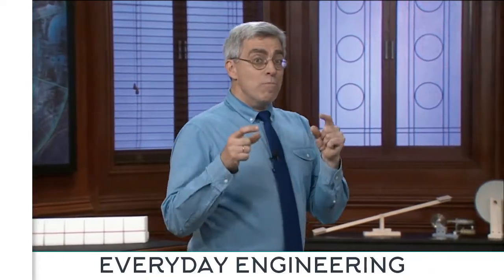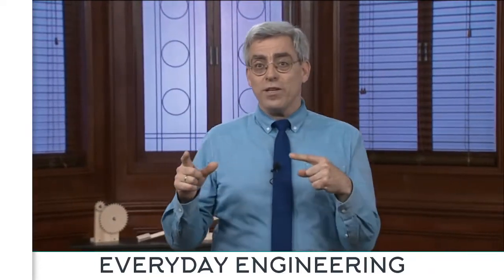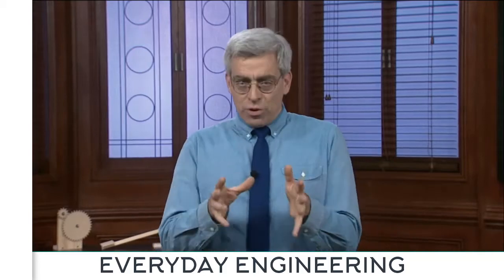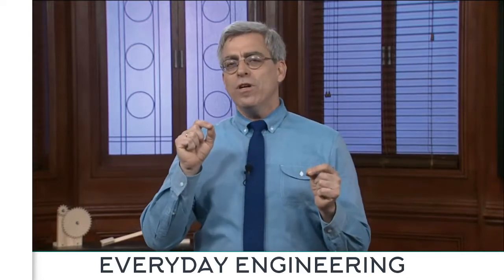And so for this more realistic utilization of living room floor space, the code-specified loading, 40 pounds per square foot, is quite reasonable. Now, through this discussion of live load, I hope you've gained some deeper insight into the practical value of building codes. In the absence of the code, determining an appropriate live load to represent a specific planned usage of residential space would have required extensive research and considerable engineering judgment. But the code made this task easy, providing us with a single number, 40 pounds per square foot, that was formulated by experts and validated through its use in the design of many thousands of structures.